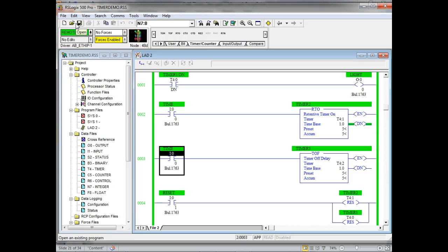So instead of, I said that wrong. So we'd use a normally open contact because it would be true until it meets its time, and then it would turn whatever I want off, unless I want it to work anyway. You can use normally opens or normally closed contacts. It's up to you on which way you go, right? You understand? Everybody okay?